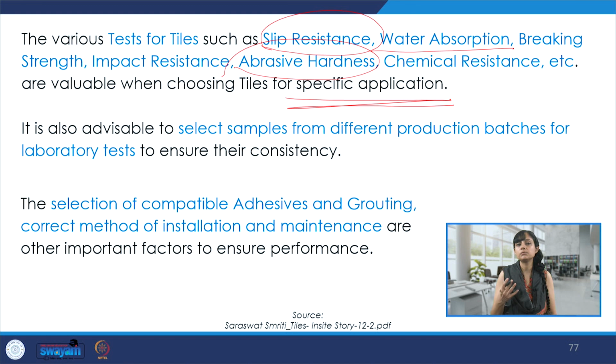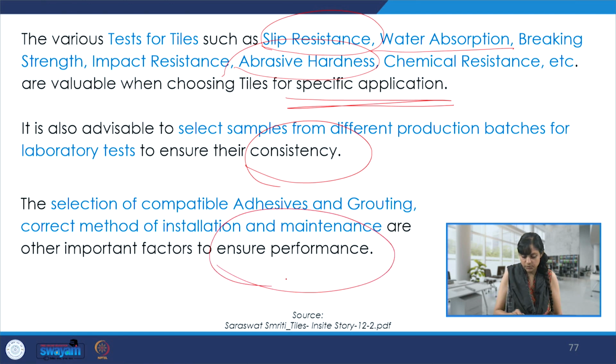It is also advisable to select samples from different production batches for laboratory tests to ensure consistency. And the selection of compatible adhesives and grouting, the correct method of installation and maintenance are all important factors to ensure the best or optimal performance.